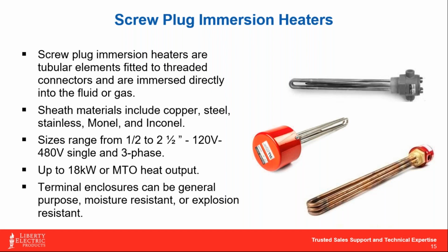A common application for these is something like an electric water heater. You could go find one of those in almost any hardware store, and when you remove the element, you'll notice it's a screw plug immersion heater. These can come in several different sheath materials as well. They go all the way up to about 18 kW, which is a pretty significant heat load. I think that equates to around 52,000 BTUs. So you can get quite a bit of heat out of these.